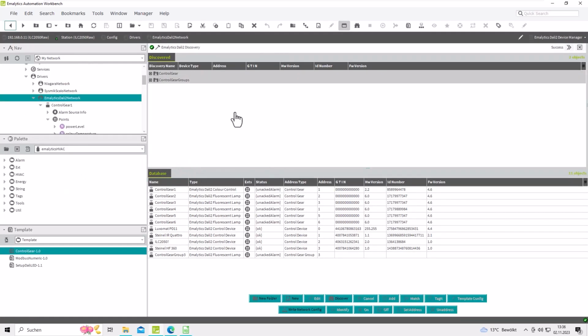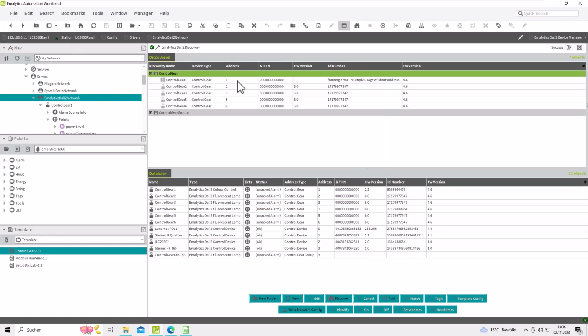When we now start from scratch and implement all configurations over the bulk deployment, let us think about our control gears probably not having a correct address. So first of all, we have to do the discover, make the random addressing, and then go into the room, make the correct addressing, and then we will go on with the configuration of the control gears themselves.